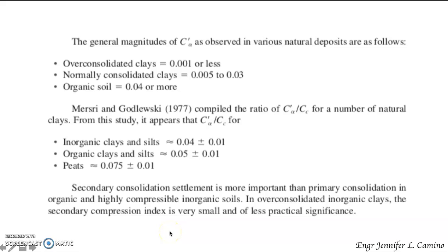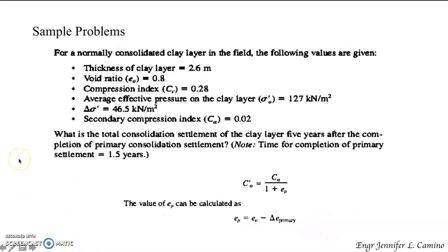Secondary consolidation settlement is more important than primary consolidation in organic and highly compressible inorganic soil. In overconsolidated inorganic clay, the secondary compression index is very small and of less practical significance. So we have here a sample problem.